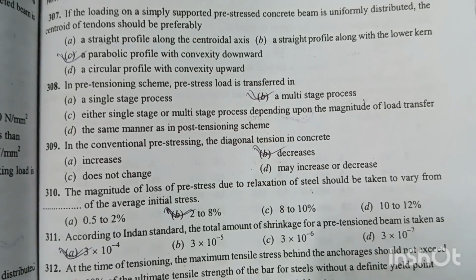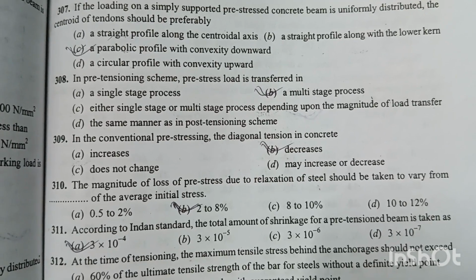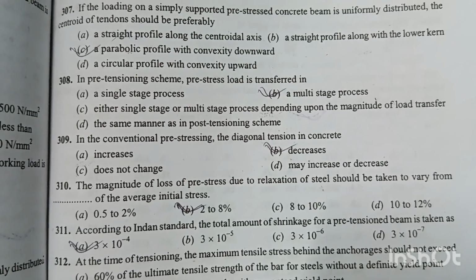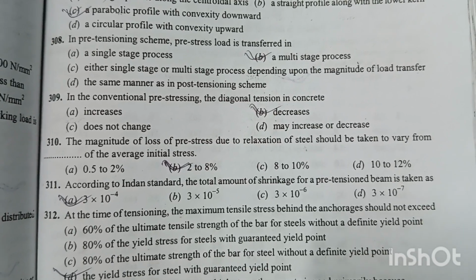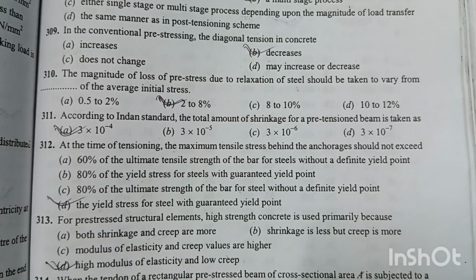Question number 311. According to Indian standard, the total amount of shrinkage for a pre-tension beam is taken as 3 into 10 to the minus 4. Option A is the right answer. Question number 312. At the time of tensioning, the maximum tensile stress beyond the anchorages should not exceed 80% of the ultimate strength of the bar for steel without a definite yield point, and option D, the yield stress for steel with guaranteed yield point. So both options C and D are right. Question number 313. For pre-stressed structural element, high strength concrete is used primarily because of high modulus of elasticity and low creep. Option D is the right answer.